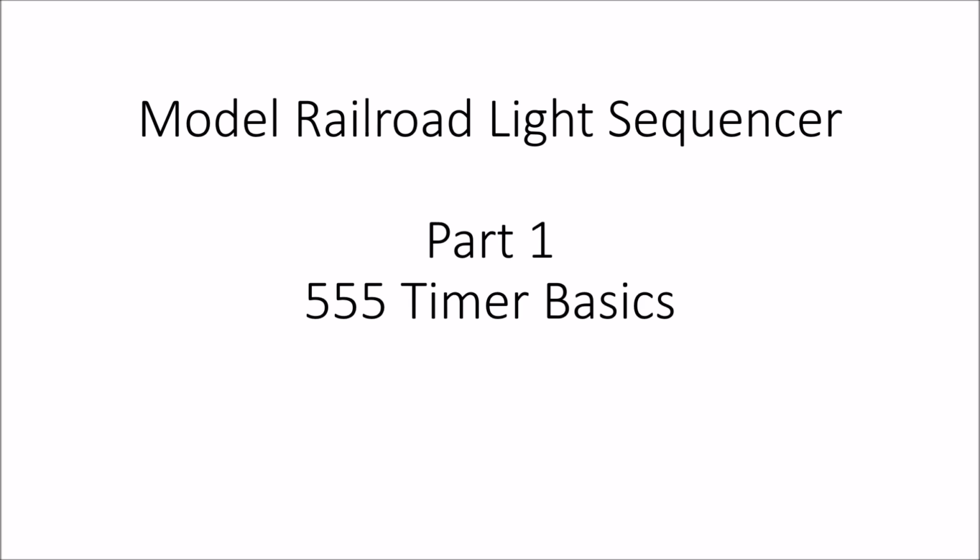Okay, let's talk about a model railroad light sequencer. What is a light sequencer in model railroading? Sometimes it's called by a different name. Sometimes they're called rig counters. Sometimes they're called shift registers in electronics. Sometimes they're called waterfall displays. Basically, they're a method of lighting up LEDs in a particular way. In our case, it's going to be a random manner to light up buildings or parts of buildings, which LEDs will go on and off.